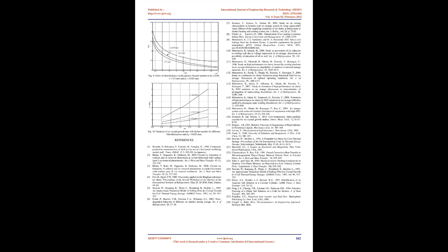Also, the results showed that the average heat transfer coefficient is almost independent of the Stefan number for different film thicknesses, as depicted in Fig 6. The variation of particle Nusselt number within the film thickness for different x locations is shown in Fig 7. It can be seen that the particle Nusselt number increases in the flow direction and reaches an asymptotic value at the middle of the film thickness. This can be attributed to the continuous increase in the particle diameter, especially in the streamlines beside the wall.